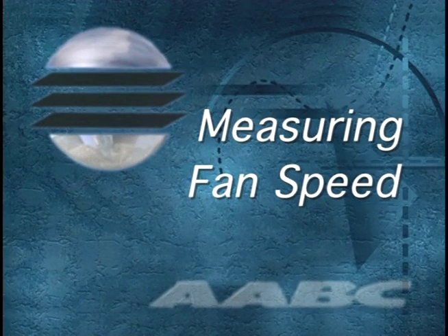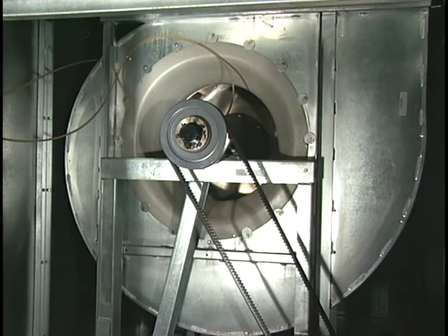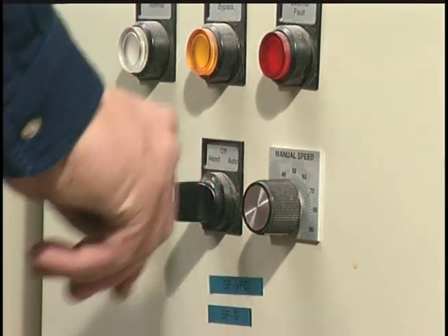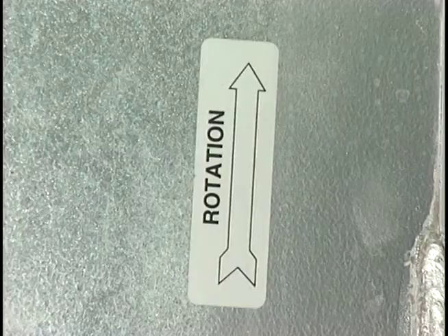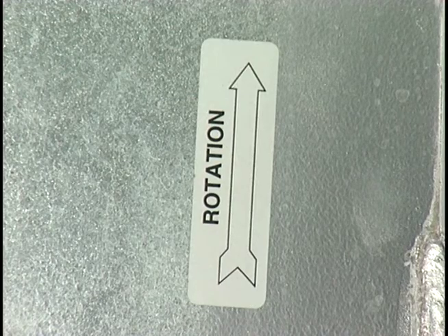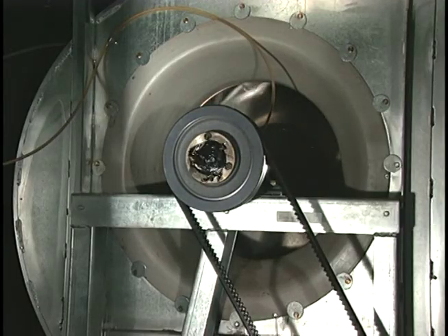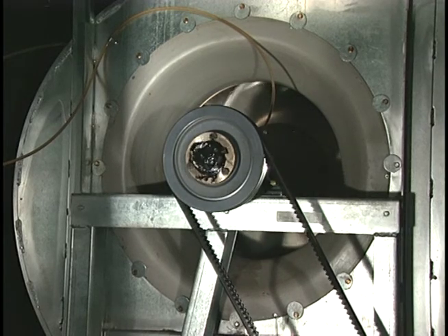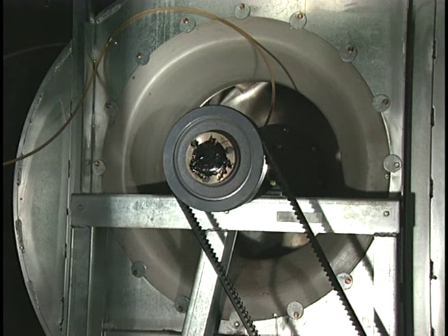Measuring fan speed. Starting with the supply fan, the technician momentarily starts and stops, or bumps, the fan to check rotation. Some fans have rotation arrows on them, but the technician always inspects the fan wheel and its arrangement to verify correct rotation. If the fan is rotating backwards, the electrical connections must be reversed before continuing.